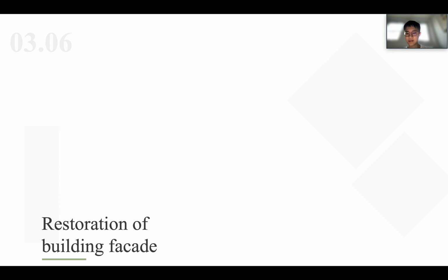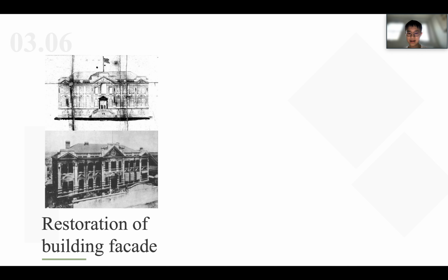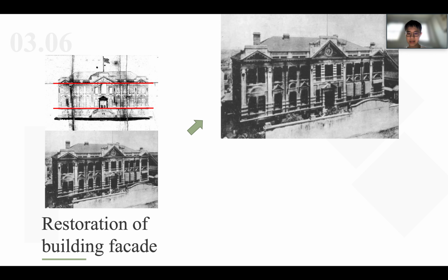In the absence of other historical data, the designer repeatedly compared the historical photos and used perspective methods to derive the control height B of the gable wall in the photo based on the known on-site building height A on the same facade. Since part A still remains today, we can measure its height and use it as the basis to calculate the height B, which has already been demolished.